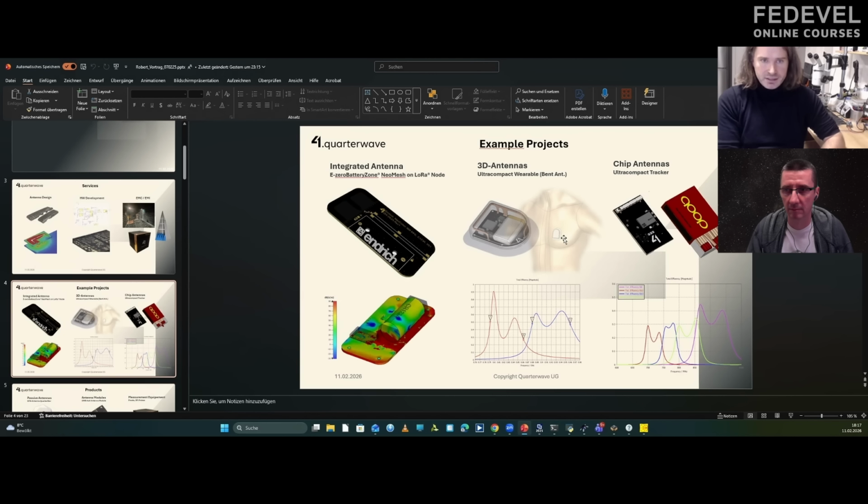And then you have a second problem because you are narrowband. If you want to overcome the narrowband, you need to switch the antenna. So you have two matching networks and you can switch between them. What we can see here on the screen is the lower LTE band, band 20 and band 8. To cover these bands, you can't do it with one matching component. You need two matching networks and you can switch between them.